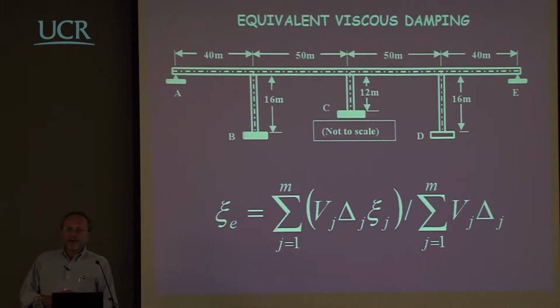In a way, I'm saying that while it is totally irrational to try to find a single force reduction factor, it is totally rational and physically sound to find a global equivalent damping, which is a factor that reduces the global displacement of the structure.